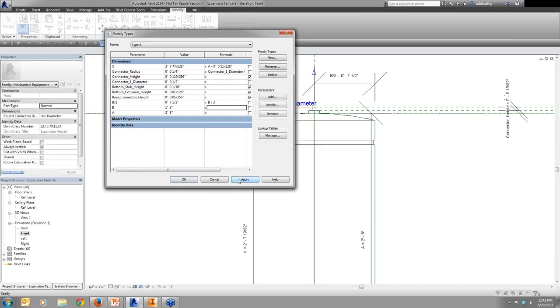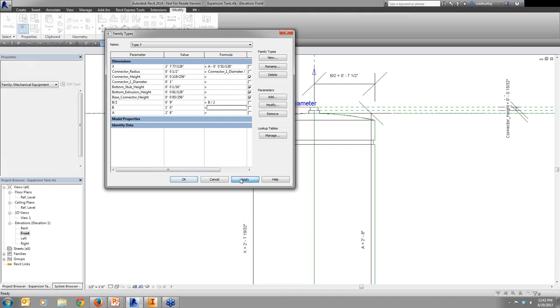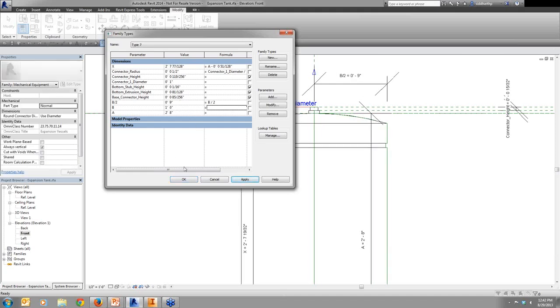That flexes fine. In fact, type 6 has a different pipe diameter, so this will go from a 1/2 inch to a 1 inch. So I can change that also and see how that extrusion and the diameter change accordingly. And I can define my seventh type to be a 32 by 18 inch, okay, with a 1 inch diameter.